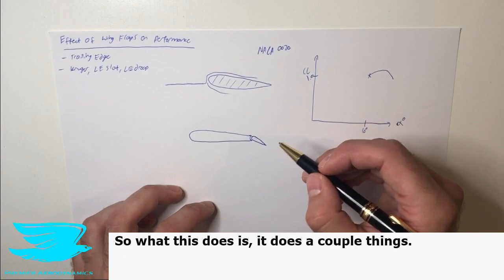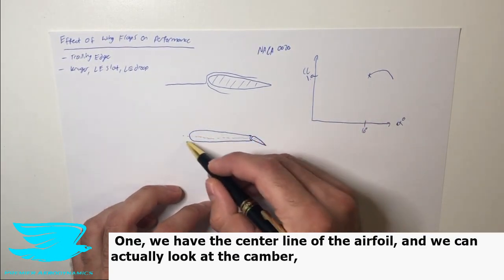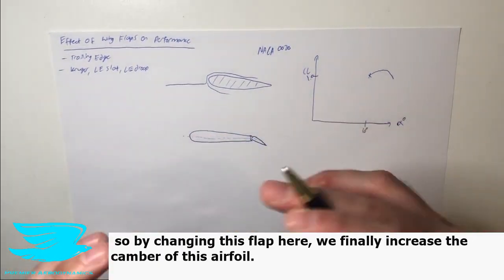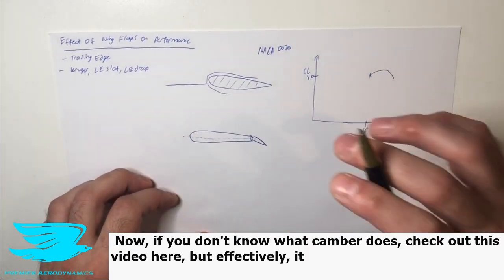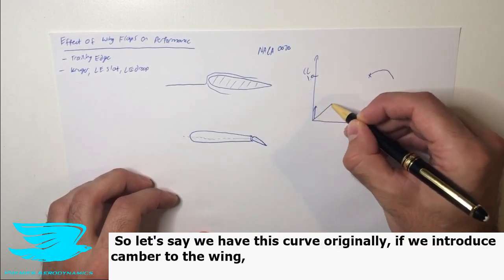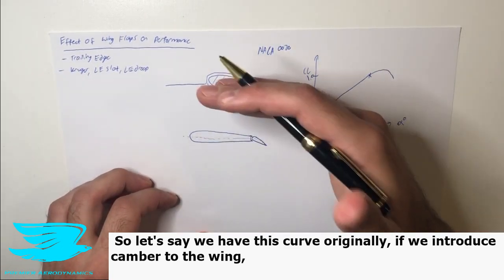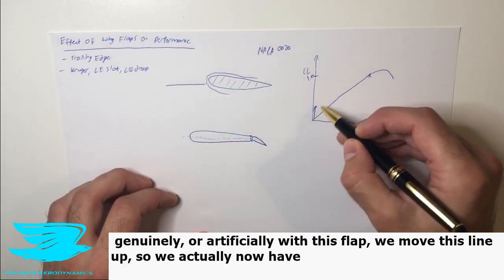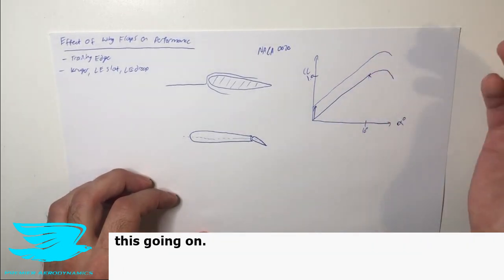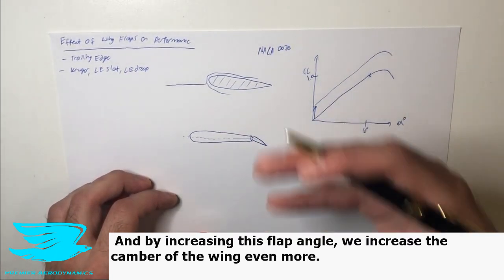So what this does is, it does a couple things. One, we have the center line of the airfoil, and we can actually look at the camber. So by changing this flap here, we effectively increase the camber of this airfoil. Now, if you don't know what camber does, check out this video here. But effectively, it increases the slope of this curve. So let's say we have this curve originally. If we introduce camber to the wing, legitimately or artificially with this flap, we move this line up. So we actually now have this going on. And by increasing this flap angle more, we increase the camber of the wing even more.